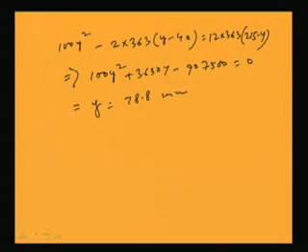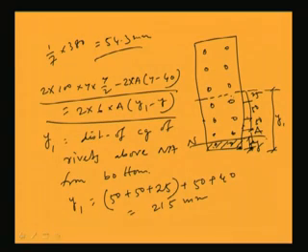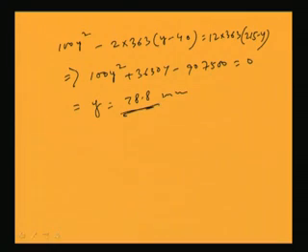So, what we are seeing here is that the neutral axis depth which was assumed at h by 7 is not correct, it is 78.8. In the earlier method we assumed the neutral axis depth is at h by 7, but in this method we are doing it more accurately, and it is not h by 7 but 78.8, close to h by 7.